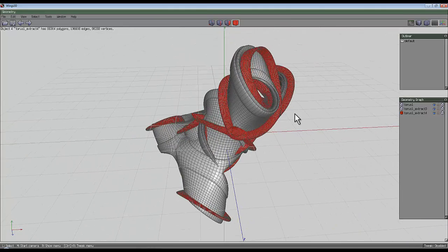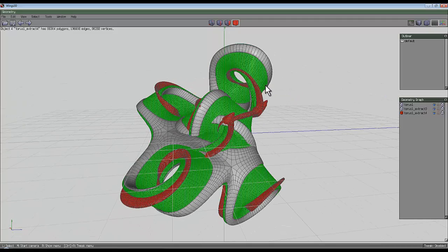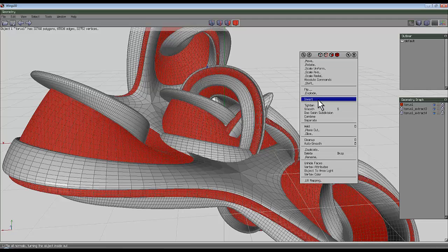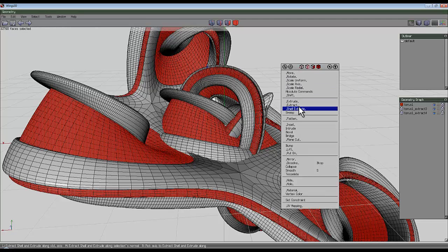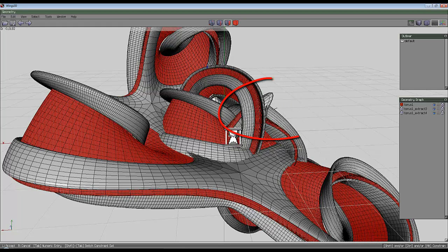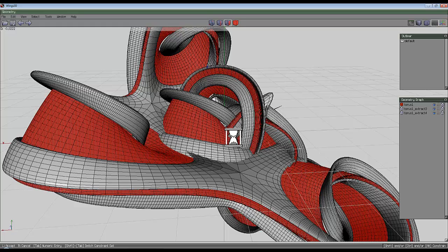My only slight concern with including this one is that the surfaces may be touching one another ever so slightly, in which case sometimes that upsets the render engines. So if I get a hold of that middle shape, just press space to deselect everything, what I could do is very carefully use the extrude key on these faces and slightly shrink the model, but it has to be done very carefully because you can see those spikes coming out of the surface there. Those would be bad.